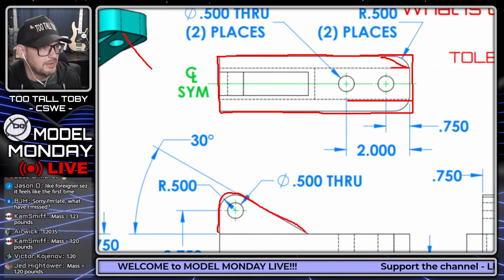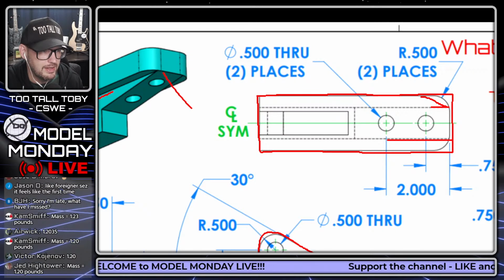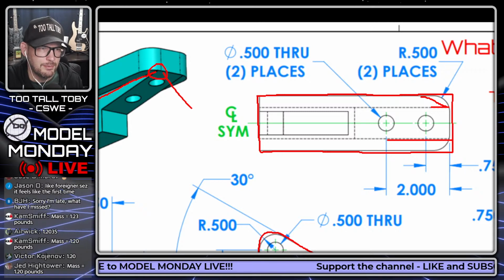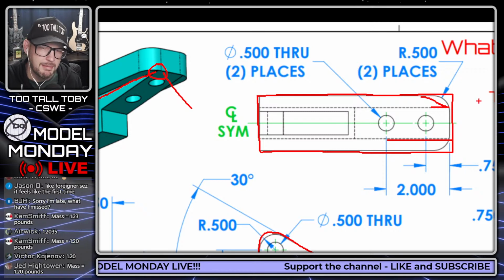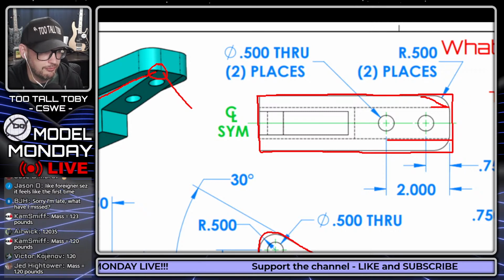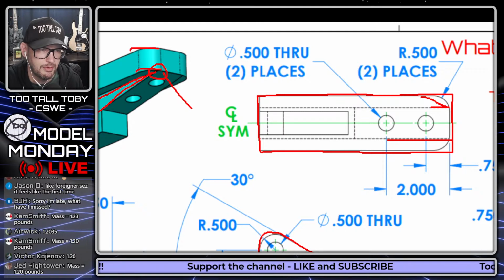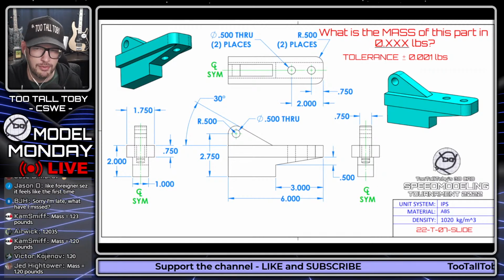Yeah, so this is a little bit subtle, but in this region up here, you can see that the center fin comes out, and it's interfacing with this fillet in kind of a weird way. Just knowing what we know about manufacturing, that should tell us that we want to make sure that we have that fillet created first, and then go back in and fill it so that we fill it around that entire corner. So that's my game plan for this design.